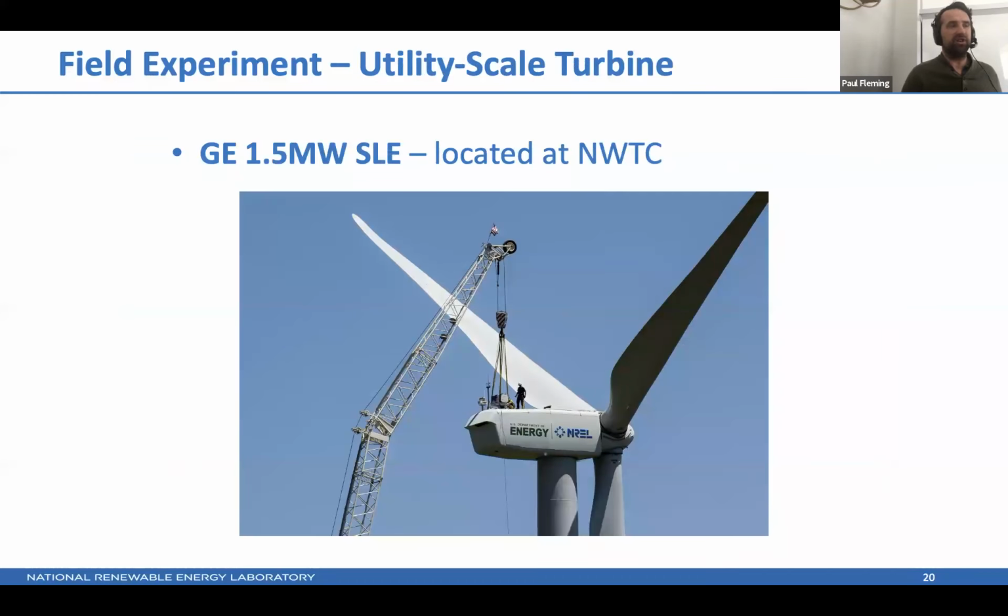So this was a study we did in Colorado. It's a subset of a much larger farm where we looked at these turbines labeled T2 and T4, and designed, using FLORIS, optimal yaw offset angles for different wind directions and speeds, and looked at the impact we were having on this T3 in the middle. So when the winds were out of the north, we could run this north campaign with T2 as the controlled turbine, and with the winds out of the south, we could use T4.